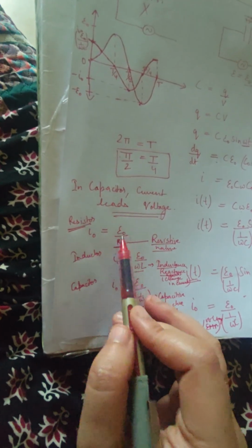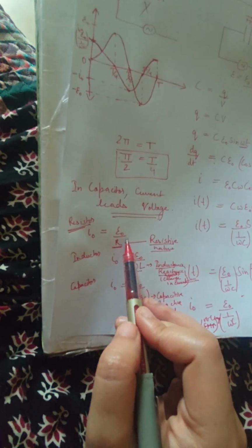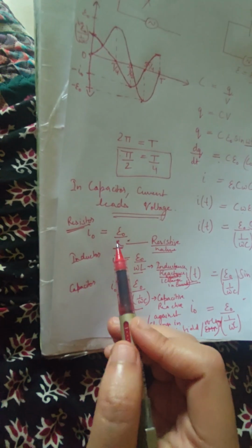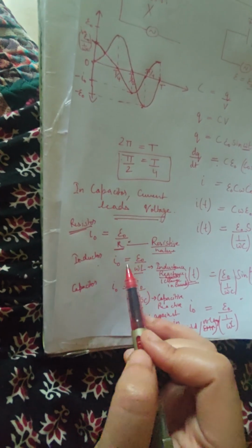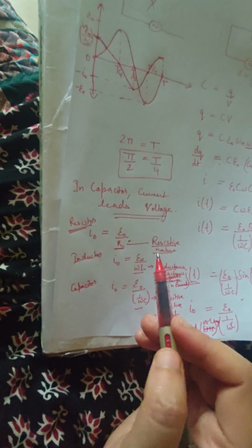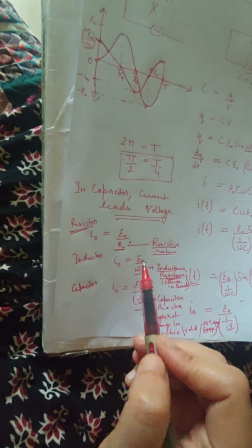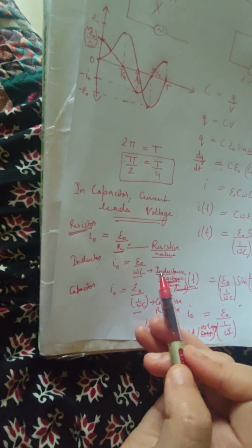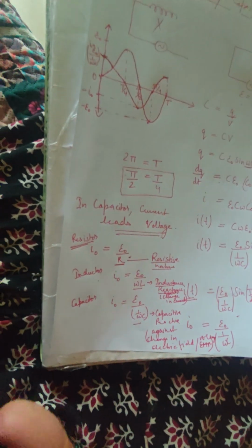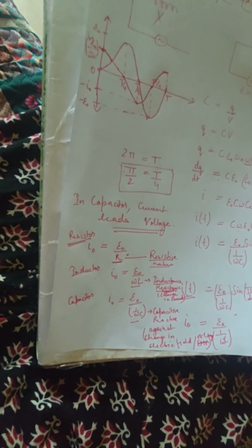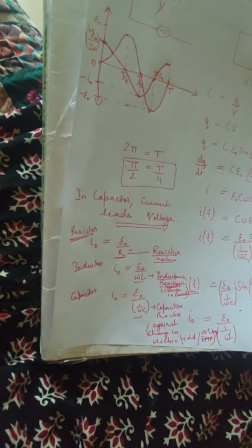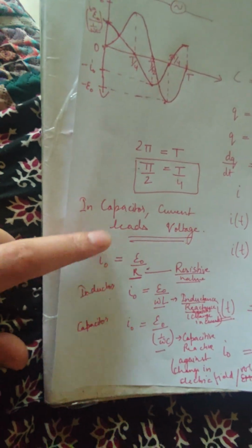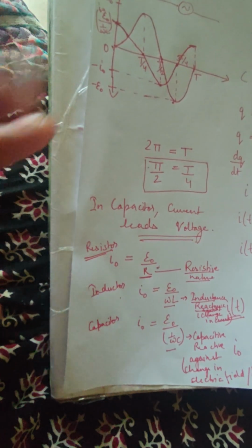So you can also see here is a resistive material that we use, a little different material. Nichrome wire we use. At times we use constantan and manganin and many other alloys which have high resistance, which obstruct the flow of current. But in the case of an inductor, we don't have a resistive material. We have a conducting material turned into the form of a coil, so that it can store some magnetic field, and the change in that magnetic field creates a kind of impedance, or I would say a reactance, a kind of resistive nature, but it's not the same as resistance. That's why we have given it a different name. Resistance can occur for DC, and resistors behave the same way for DC as well as AC.